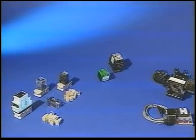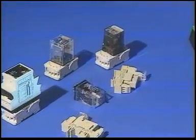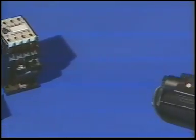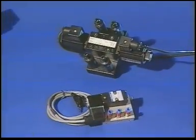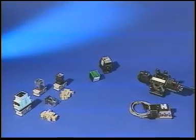The magnetic effect of current is the form of electrical energy most often encountered in electropneumatics and electrohydraulics, in relays, contactors, and solenoid valves. In contrast to resistive loads, these are called inductive loads. The electric motor also belongs to this category.